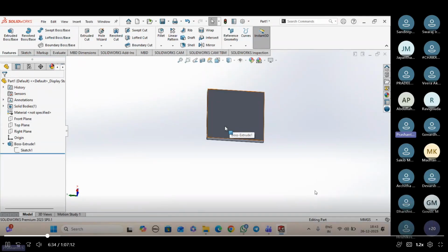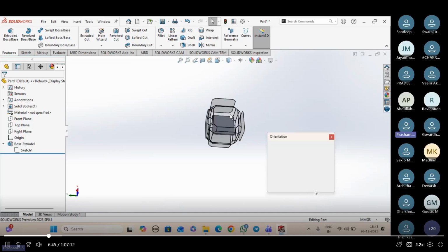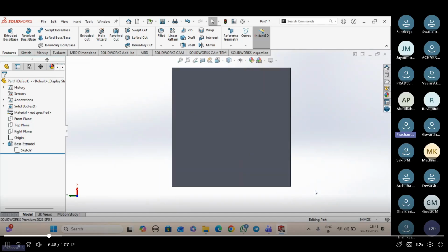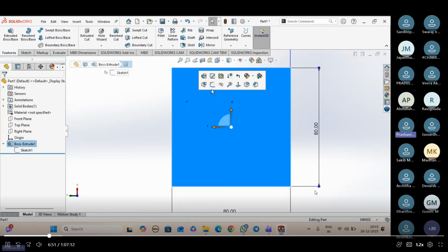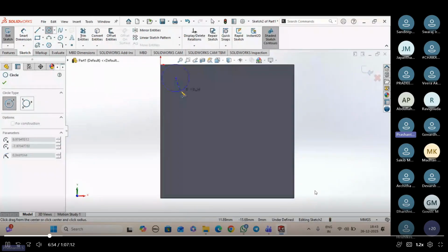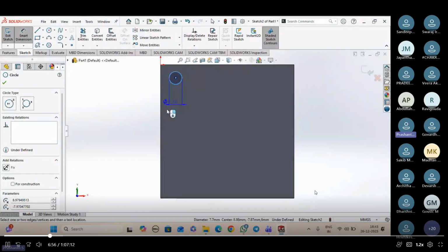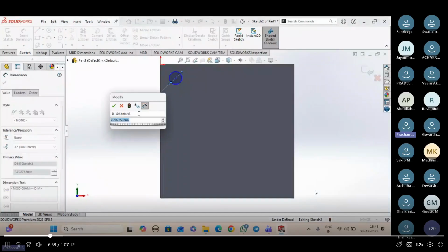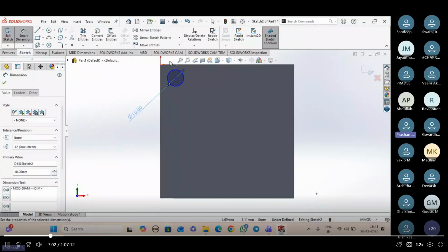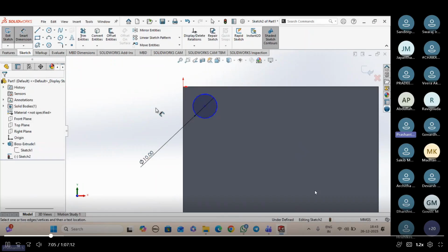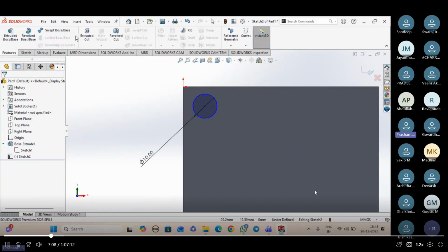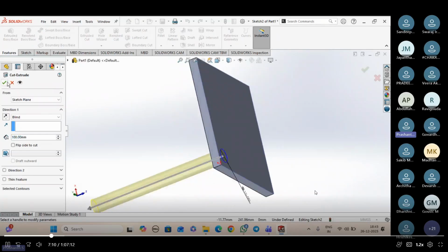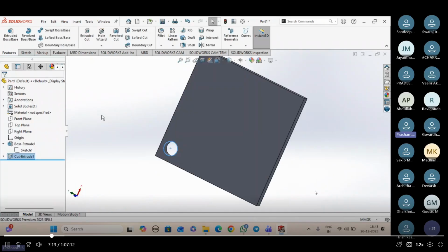But in this point, we have to clear two things. Making the tapping, or tapping in the sense what? Thread, that internal thread. Let's say if this is a plate, I will practically do it, then you'll understand. I want to make a hole for M10, for mounting an M10 bolt. So now I'll make a sketch like this. This is 10 mm diameter, and I'll just go to feature, go to extrude cut. So I have made a hole like this, just a hole.